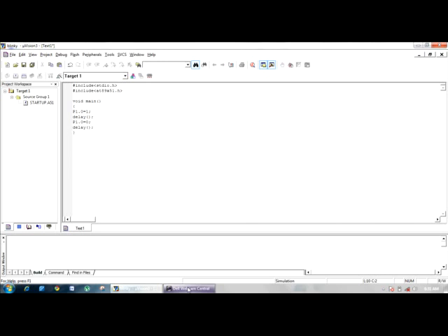Now I am going to give the function delay. int i, for i equal to 0, i less than or equal to probably 500. So actually this value will determine how long your duration or the delay time will be. I am giving 500. Any numerical value can be given.